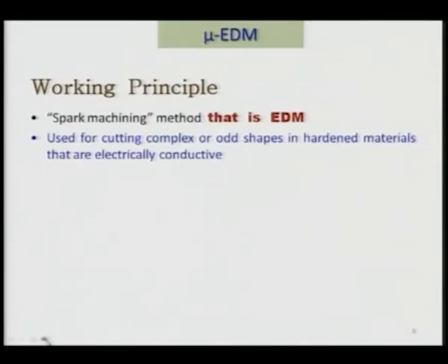It is used for cutting complex or odd shapes in hardened materials that are electrically conductive. And one more thing, it can machine very hard materials if they are electrically conducting, or you can say difficult to machine materials can be easily machined by this particular process.